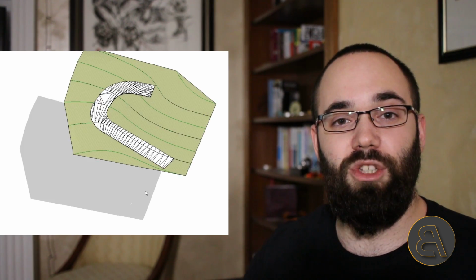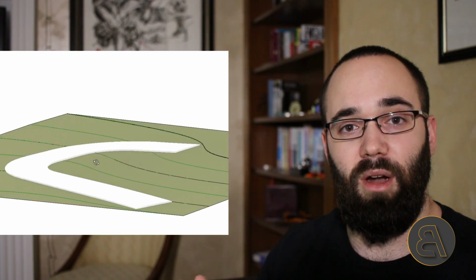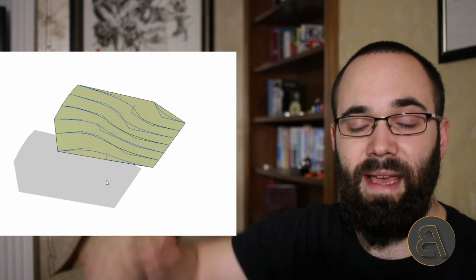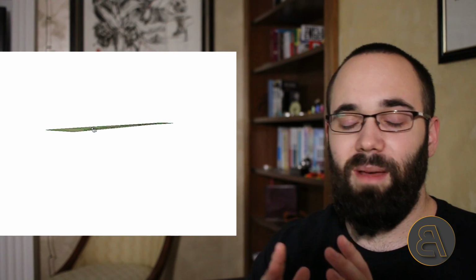And also I'm going to be showing you the really cool approach to creating topography that this plugin has, and that's the ability to just draw simple model lines in space that define the contour lines for your topography, and then you can set the elevations of all of these and turn them into actual topography. It's really amazing. It's just a few steps and you can pretty much achieve anything, and it really saves you a lot of time when it comes to working with topography. It's truly groundbreaking. Okay, so that's what this tutorial is going to be all about.